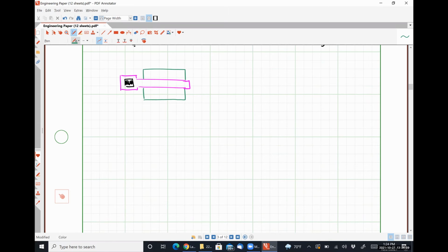So this is a pretty basic transistor where this is our gate, this is our drain, and this is our source. Because the polysilicon has some finite resistivity we've talked about previously, that means the gate has some resistance. Because the active regions have some finite resistivity, that means the drain and the source look like resistances as well.